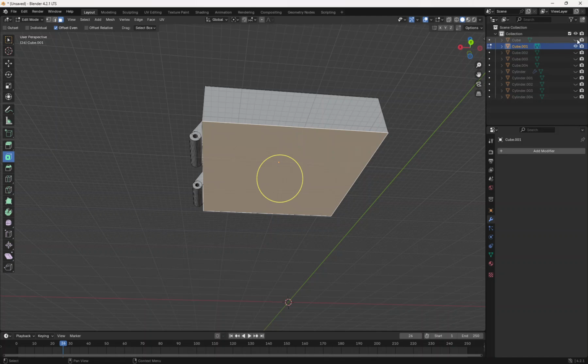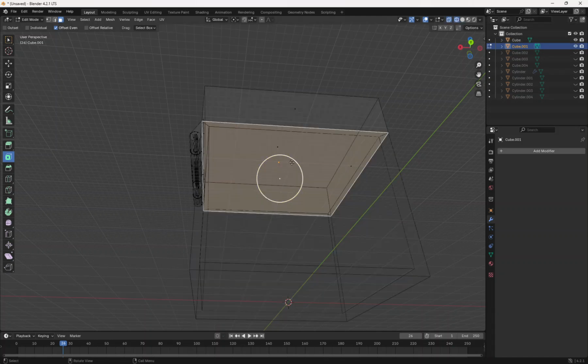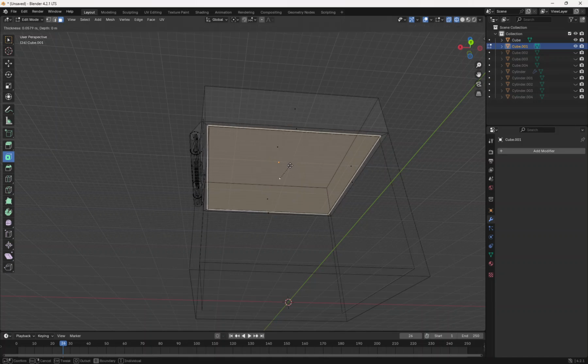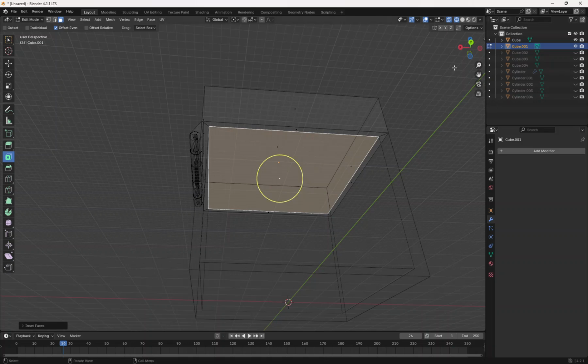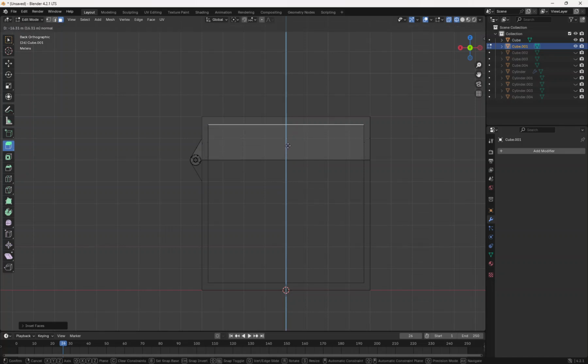go to insert faces. I did find this was helpful to be in wireframe mode. This way we can pull it in and just try to match that up to the bottom box that we just extruded, and then go to the y-axis and extrude the region, and then we can just drag that up to where it's kind of parallel. We have a nice, this gap here at the top is the same-ish as this gap, and then we're done.